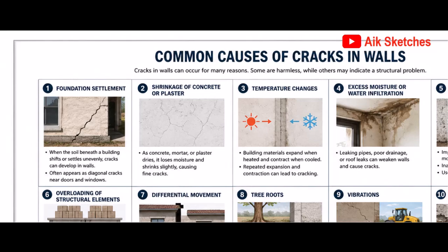The second one we'll be looking at is shrinkage of concrete or plaster. As concrete, mortar or plaster dries, it loses moisture and shrinks slightly, causing fine cracks. When concrete or plaster shrinks, it's another common cause of cracks in walls.